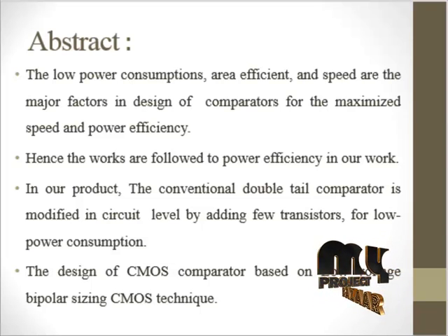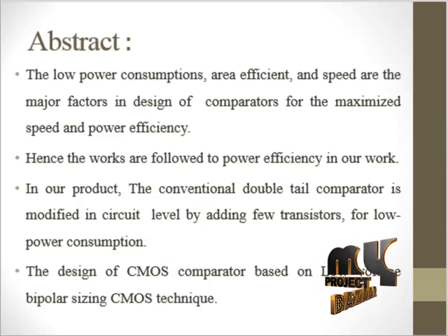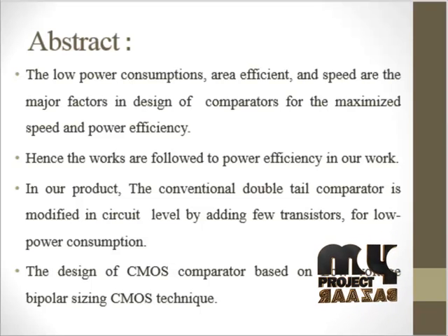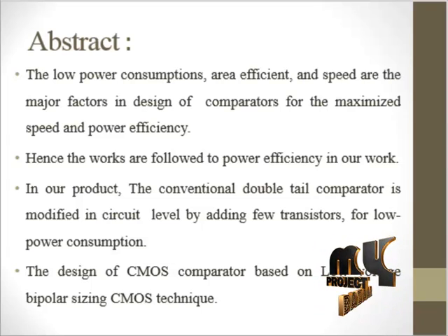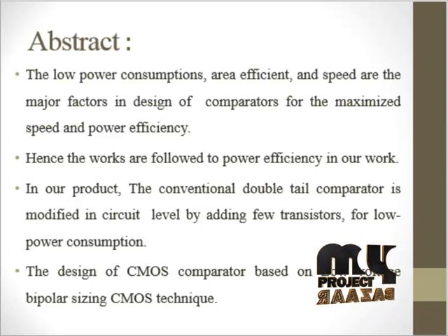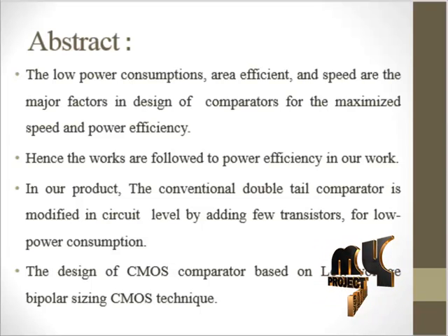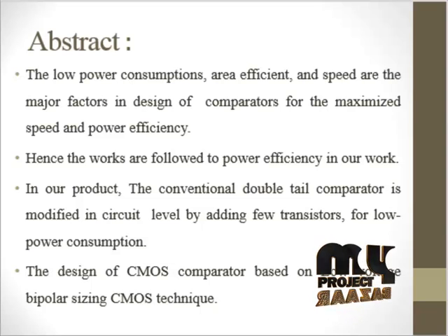In the conventional comparator, during and after the latch process, a large amount of the output capacitors of the pre-amplifier stage consume power, so the pre-amplification stage is prevented from operating.